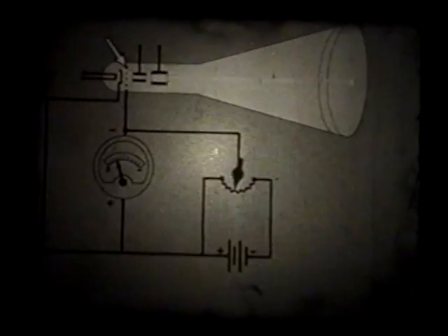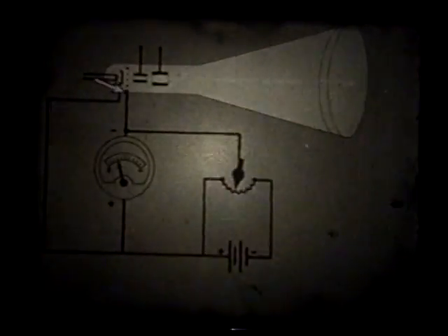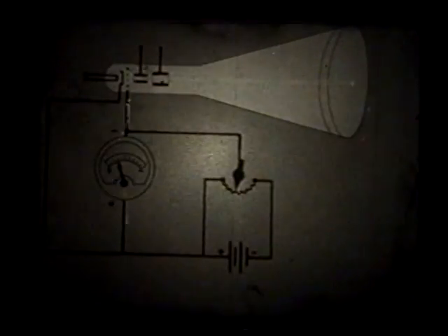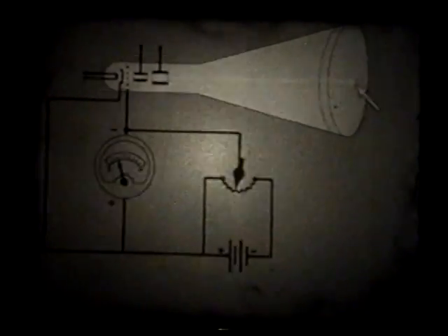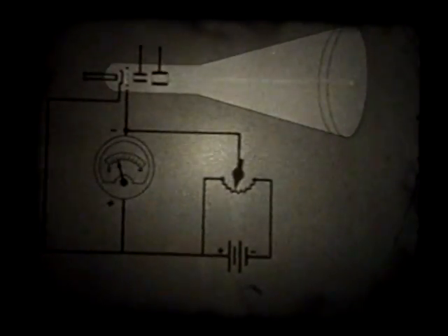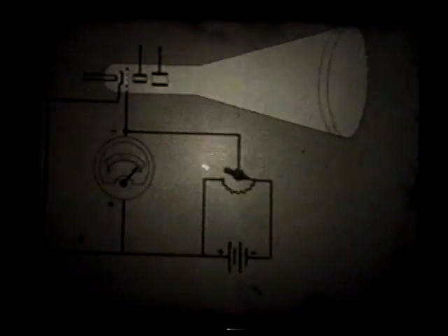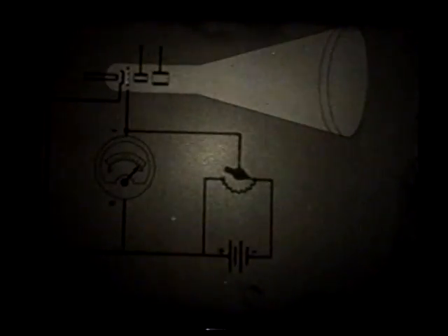This electron beam bombards the fluorescent screen to form a bright spot on the face of the tube. The intensity or brilliance of the spot can be controlled by varying the voltage on the grid of the tube. When the grid carries a small negative potential, the spot is bright. When the voltage applied to the grid is highly negative, the electrons are held back and no spot of light is formed.